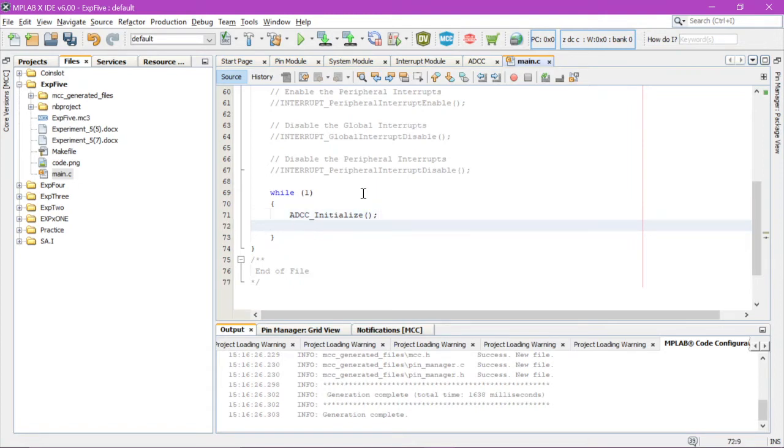After that, we'll ask if it will convert the value that is analog and compare it to 512. The reason for that is that the analog signal will be comprised of a value from 0 to 1023. So if it is turned all the way counterclockwise, it would be 0. If it is turned all the way clockwise, then it is 1023. The halfway value would be 512.